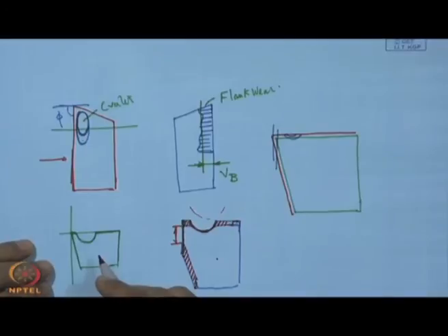Now, what is important here is that this test for wear should also be conducted, and it is very important, particularly when it is a high speed operation. In that case, it is not the question of force or chip thickness, but it comes down to the wear on the cutting tool, which changes its geometry and position from the contact surface with the job.